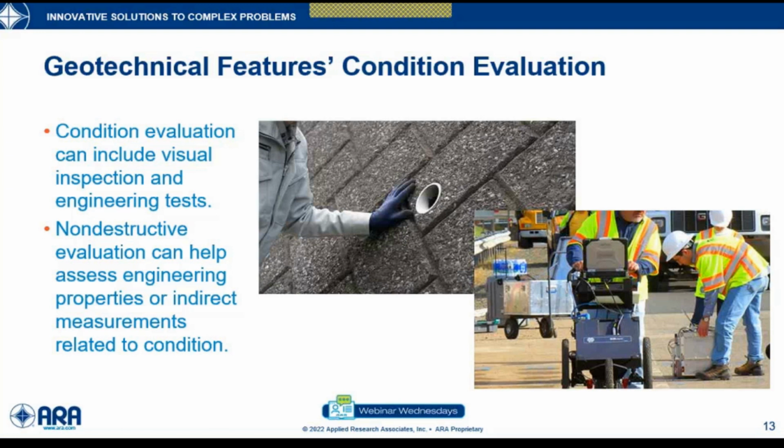But going back to the concept of risk-based data collection, and you will hear me repeat the terminology risk here over and over, one approach would be to assess the risks associated after visual inspection. So for example, if you have an asset that has been there for a while, it's showing a lot of deterioration at the surface, it may be smart to go back and collect engineering measurements and more in-depth inventory. But at the network level, a visual inspection may be the procedure to follow at this stage, as long as we have limited engineering measurements to collect at this stage.